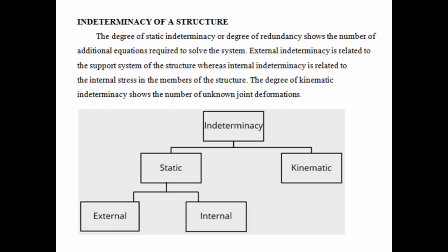And next, indeterminacy of structures. The degree of static indeterminacy or degree of redundancy shows the number of additional equations required to solve the system. External indeterminacy is related to the support system of the structure, whereas internal indeterminacy is related to the internal stress in the members of the structure.